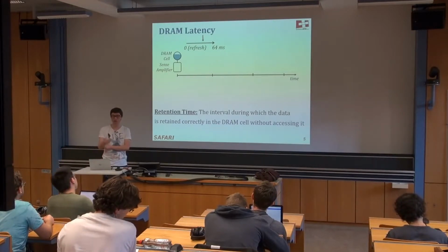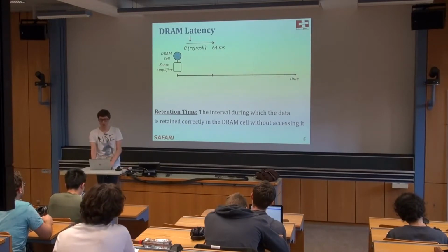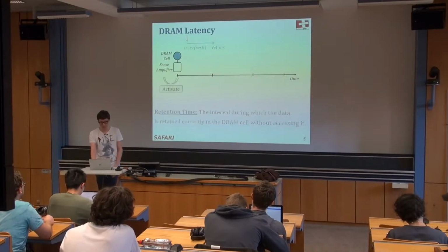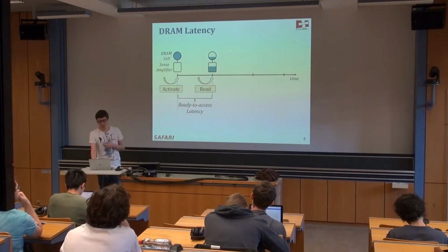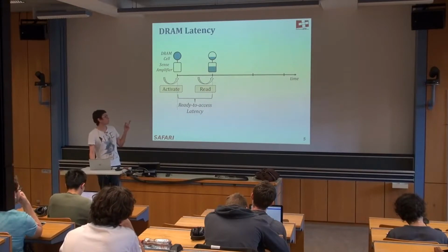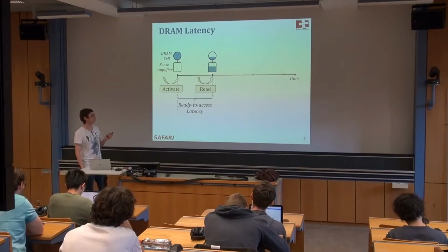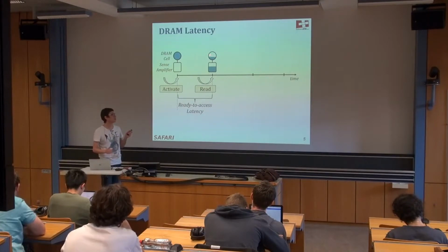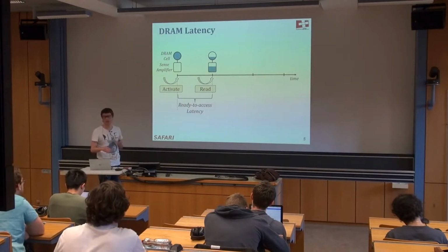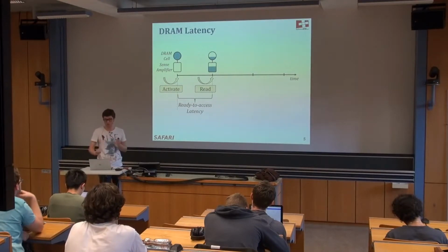But we still refresh at 64 milliseconds to ensure that everything goes well under different conditions. Okay, so when we activate, after this ready-to-access latency, where the memory controller can issue a read operation, this is what happens to a DRAM cell and sense amplifiers over here. It is not fully charged, but they all contain some amount of charge that can correctly drive the rest of the circuitry, so we can read and write data